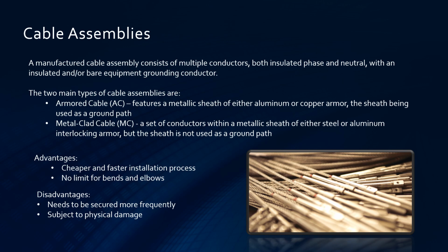The advantages is it's cheaper and faster to install, and you can kind of maneuver it how you want to. There's no limits for how many elbows or turns you have. Some of the disadvantages is it needs to be secured more frequently, and it is also subject to physical damage.